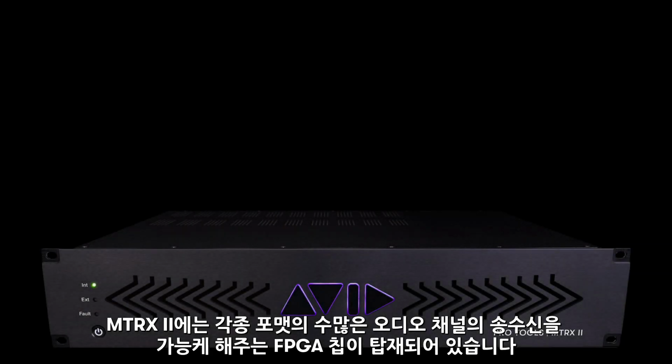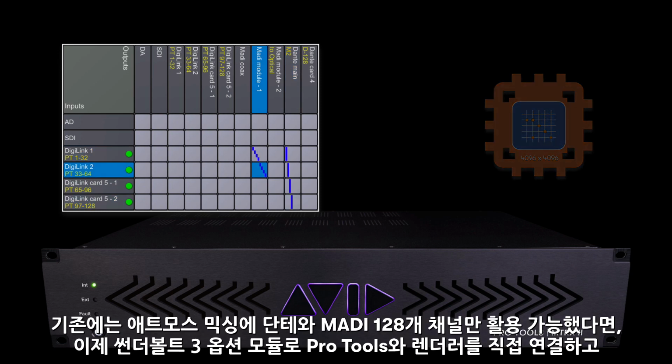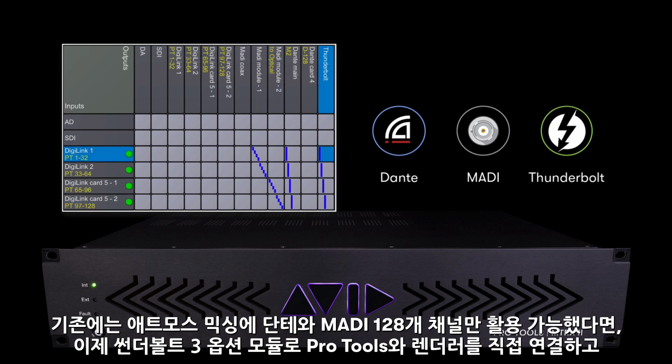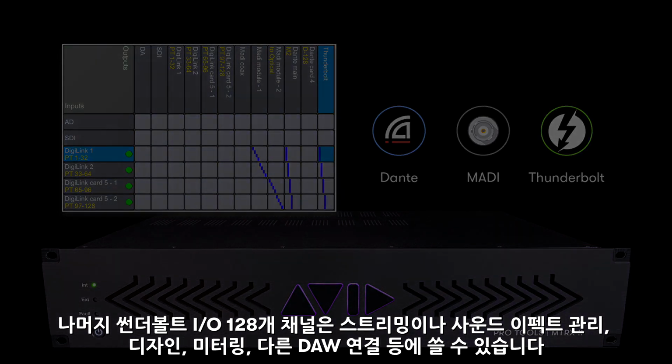At the heart of Matrix II is a massive FPGA capable of routing thousands of channels of digital audio to and from a myriad of different formats. For Dolby Atmos workflows up until recently, Dante and MADI have been the I/O formats of choice, capable of distributing the 128 channels of I/O necessary for full Atmos. Now with the Thunderbolt 3 option installed in Matrix II, we have a streamlined solution which can effortlessly connect Pro Tools to our Dolby renderer while still leaving 128 channels of Thunderbolt I/O for connecting streaming services, sound effects management, design, metering, and other DAWs.